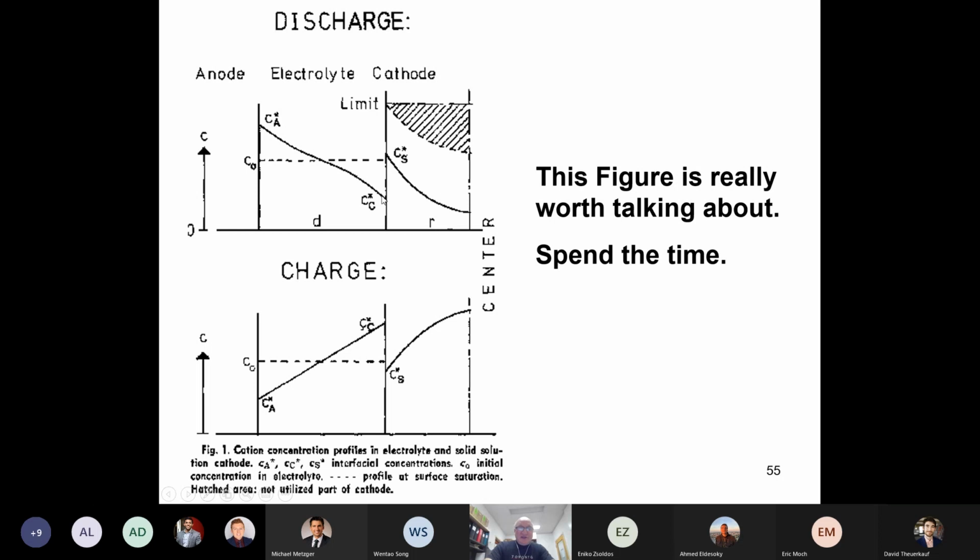So imagine that this center line was right here. Can you see my mouse? Yep. Yeah, so imagine the center line was right there. Well, then the amount of missing lithium when you get up to the top line is just a tiny little triangle. So for high rate cells, people will typically use small particle diameter positive electrodes and graphite. They'll pick smaller diameter ones. Make sense? Yep, thank you.